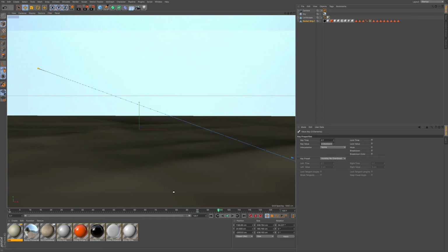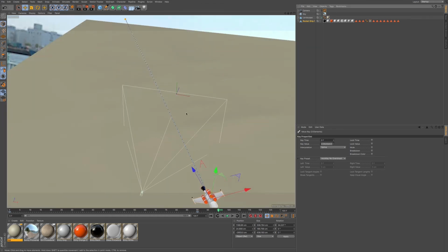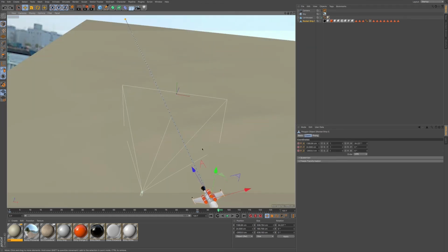And maybe I also want to give this sort of a bend to our animation. So let's unlook through our camera. Let's start our auto keying. If I go somewhere in the middle of our keyframes, turn on auto keying, and then maybe move it over to the side here, you can see this nice bend that we have to our animation path.